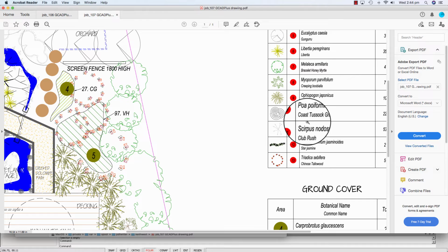So there's a simple reason why this particular user was not able to print using PDFWriter. The whole contents of the design, which was put into, of course, a floating viewport on the layout page, was put on or set on a non-printing layer. Once that was changed to a layer that does print, the problem was resolved.